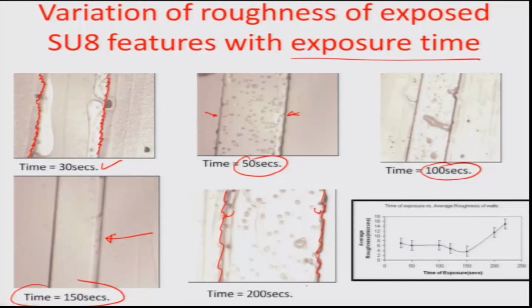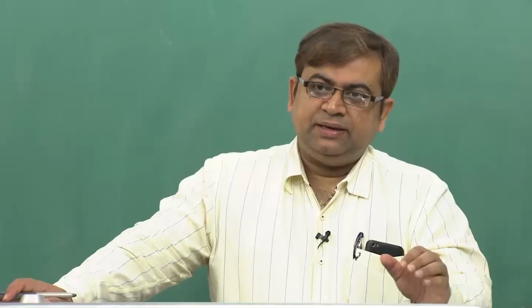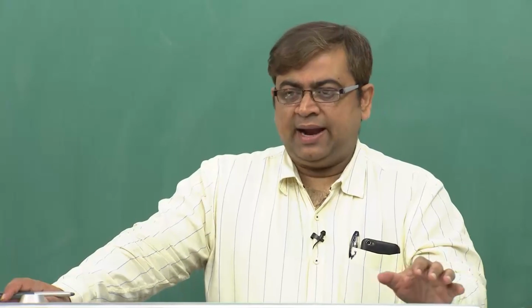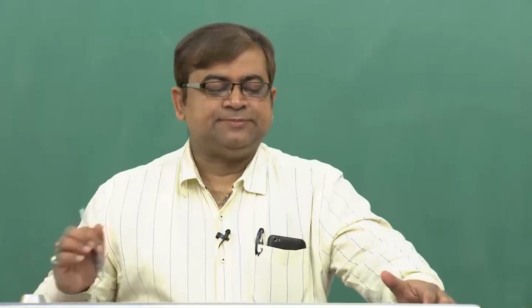So there is a recipe making which is involved in this photolithography process almost always, where all these parameters, including the exposure time, the development time, etc., and even the way you are heating is to be looked into in great detail, and many experiments done to give you a good resolution of the printing process, and these are now standardized, and the fabs which are there for doing all this lithography driven work have a very standard protocol, where you will have a high quality maintained within a controlled environment because of the repeatability of the chemicals used and the environment and the heating which is being applied as stimulus to structure these resist materials.